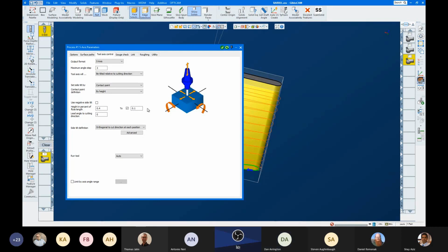So if we were using a ball nose end mill, then your scallop height would be about the same, as long as you're not past the radius for your starting. So if you used a 20 millimeter ball and it had 20 millimeters of total flute length, then halfway, or 50% up, would be where the radius on the ball nose end mill starts on that tool.